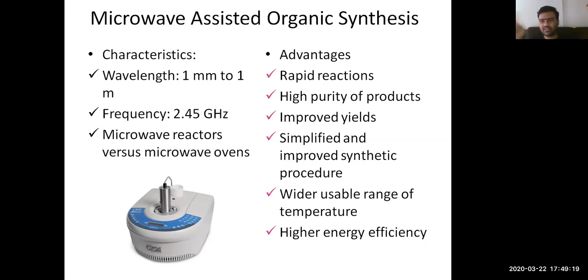These microwave radiations go and strike every wall within the cage-like structure that the domestic oven has to offer. And these will establish what is called a static or stationary wave. After it goes on colliding, it'll have some pathway wherein it will collide. So there'll be some parts which will be hot spots, and there'll be some parts which will be cold spots within the microwave oven itself. You understand? It's not a uniform heating across.